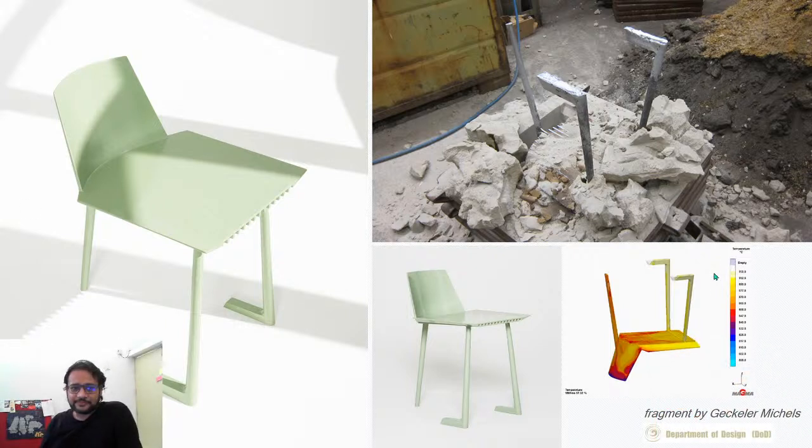Right, so what you can see here is a simulation of the casting process. It is possible to simulate casting. I think this one was done in a software called MagmaFlow, and you could do that in something called ANSYS. There are a lot of other software packages which enable you to see how the flow happens and how it cools, and you can actually get a good idea of how the casting will happen. So in this one, for example, after the whole molten material is poured in, you can see the red locations are slightly lower temperature, and the bluer locations are even lower than that. So this part cools down faster, and the yellow part is at a much higher temperature. This scale is in temperature, degree centigrade. Okay, so that's the idea.